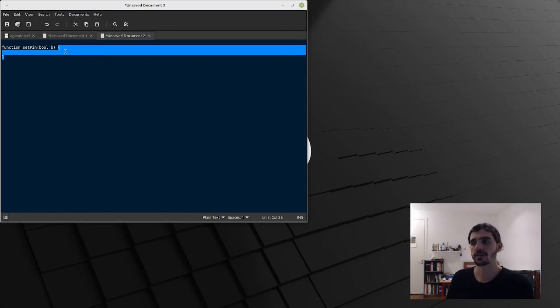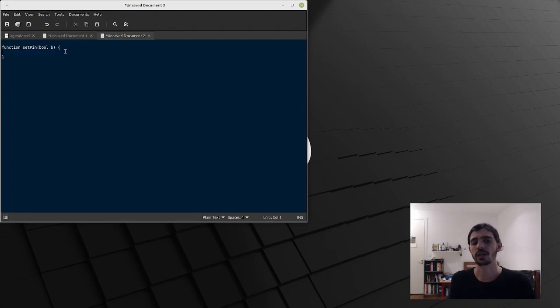They only know that there has to be a pin. So really, the developer of the library is not going to put any code inside of this setPin function. It's just going to be a floating function, an abstract function that, hey, we'll tell the user, you need to implement this setPin function to interact with my Wi-Fi device.